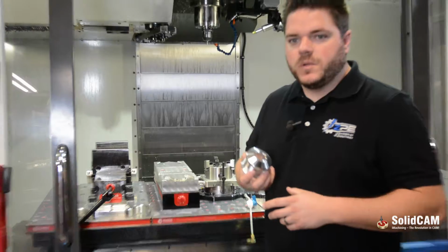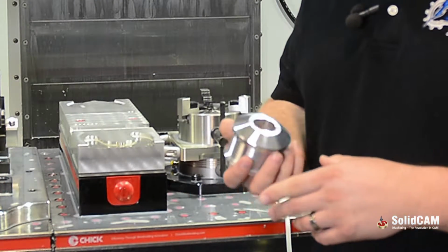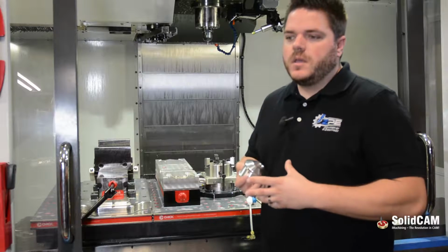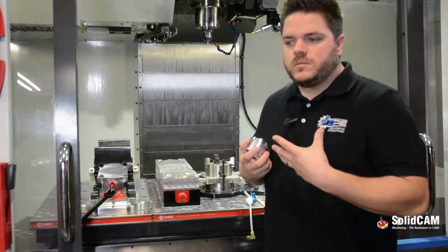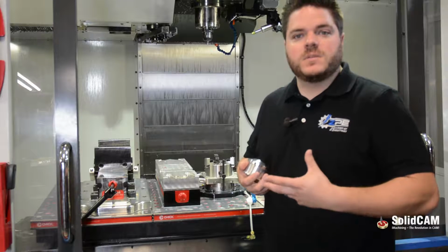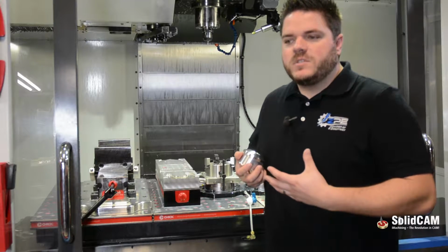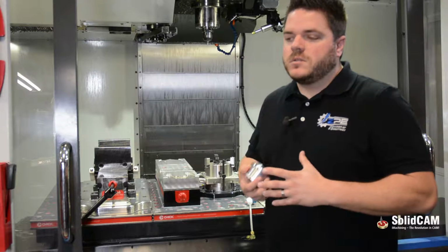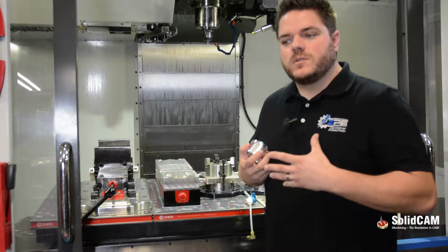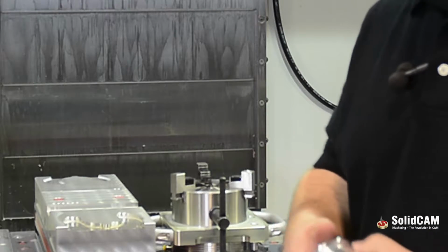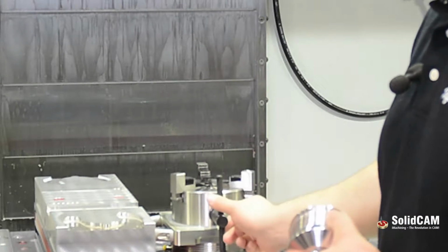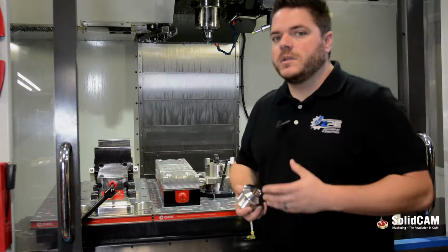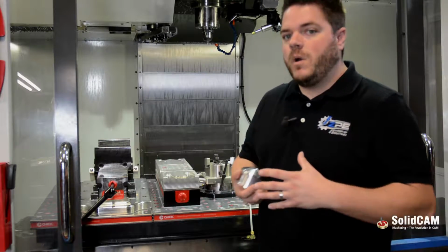So right here we have a good example of one of our parts. When we make our parts, customers order them in sizes of basically 25 thou increments sometimes. So to have a fixture to fit all of our parts on the inner diameter and the outer diameter is somewhat challenging. Sometimes when we get specialty orders for unique sizes, we resort to using an automatic 3-jaw chuck, which naturally doesn't carry real good repeatability in the X and the Y.